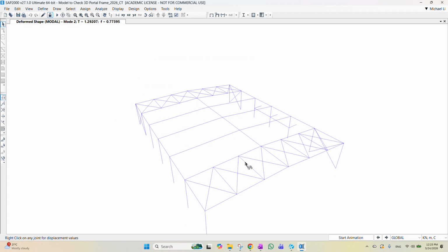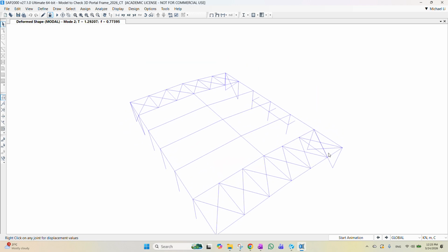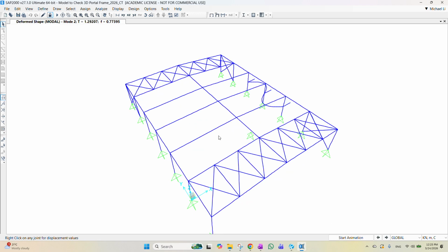On the other hand, you can see the left bay only has one cross brace. That means one bay here versus two bays over here. The two bays obviously take twice as much load as this member here. So the building, I think, in the longitudinal direction is probably exhibiting some torsion because the stiffness is not evenly distributed through the frames.